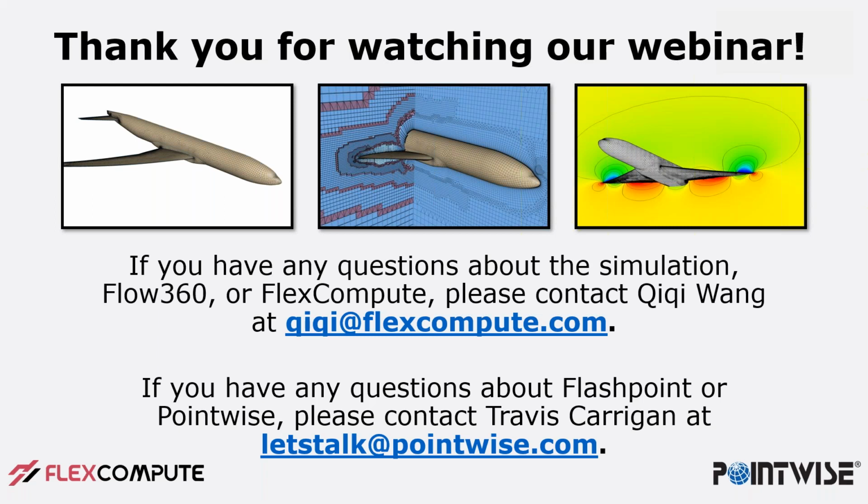Maybe I should mention this, one of the advantages with Flashpoint surface meshing: it is a very much top-down meshing tool that provides a lot of automation, but you can still use all of the bottom-up tools in Pointwise to modify that mesh. That's really important. We didn't sacrifice the manual tools for automation. They can live together, and they do in Pointwise. You may get to a certain point in the automatic surface mesh creation process where you like what you're seeing, but you want to tweak one or two things. You still have all of those tools at your disposal.